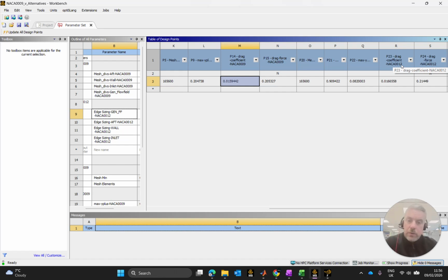So the 0009 and the 0012, the two airfoils that we're comparing here, have the same thickness, different profiles, which results in different chord lengths. The 0009 being a longer chord length now than the 12. So that is, as I said, counterintuitive. Maybe you would think in first principles that for a given frontal area, we should negate any variations in drag due to frontal area, because the left balances the right. The two airfoils are the same, so they should, in principle, cancel each other out.